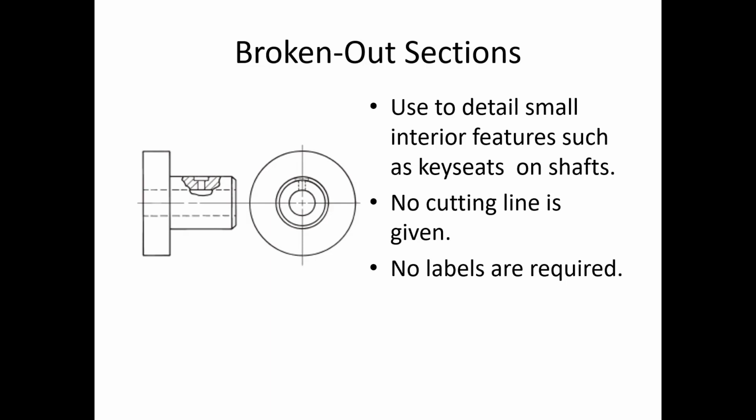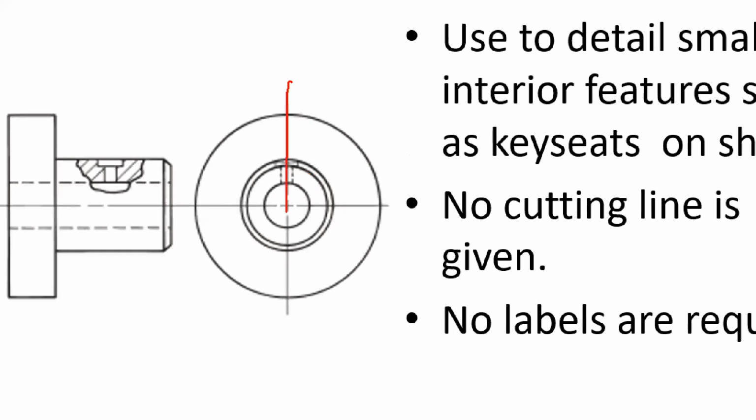So the section view is just that little piece, really. This is a regular front view, just like normal. And so we're putting a section view in this case in the drawing that we've already done. We're just peeling back a little bit of material to show one specific feature on a part. Instead of making a whole section view, you could have just as easily done a full section view here, or a half section even, and section the whole thing.